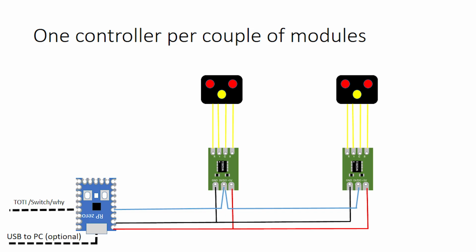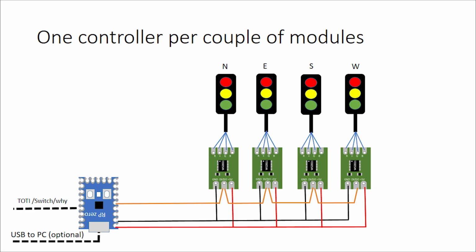That's very, very similar, only it's a set of level crossing lights, and I'm using the daisy chaining of the NeoPixels. Notice you don't need to put anything on the end. The top end of the chain, the last output, doesn't need a resistor or a terminator or any of that stuff. You just leave it floating in the breeze. I'm using my one controller. Let's put more on it.